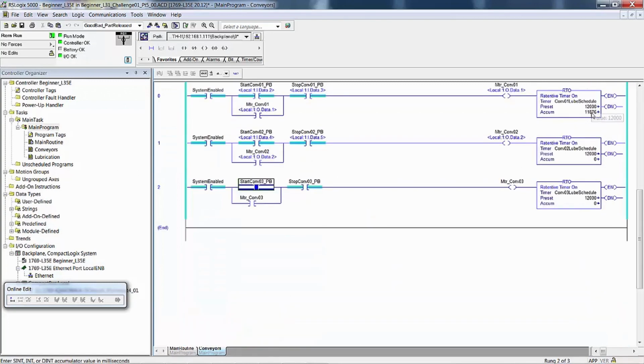It's not done, and we have no way to reset it unless I'm going to click there and type in 0. We carried over that number when we copied and pasted rungs from one routine to the other. So back where we were at. The last question was, are the timers accumulating? No, they're not, even though those two rungs look true.